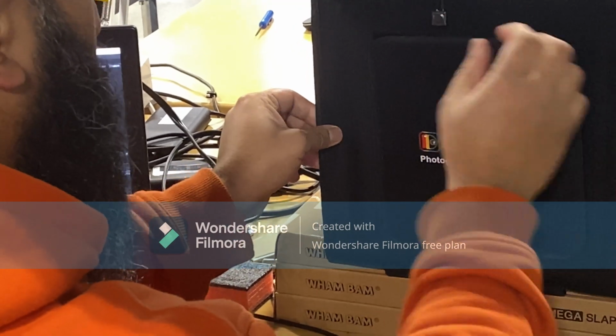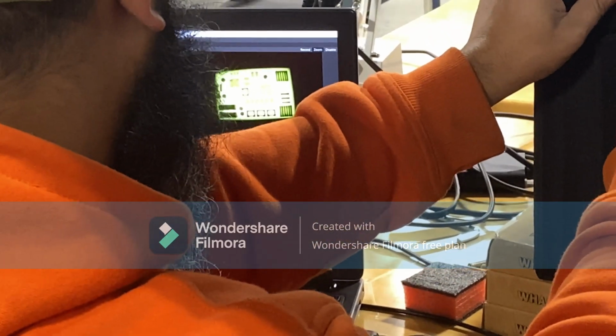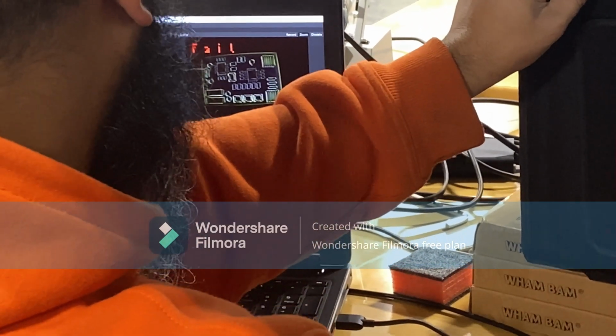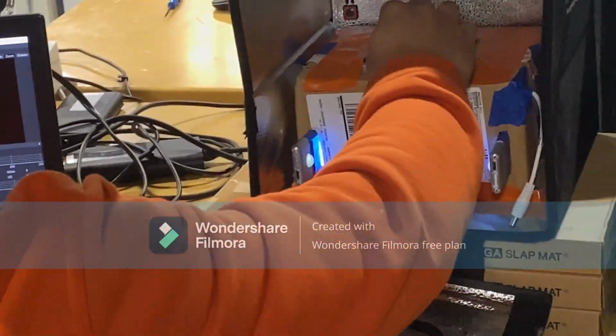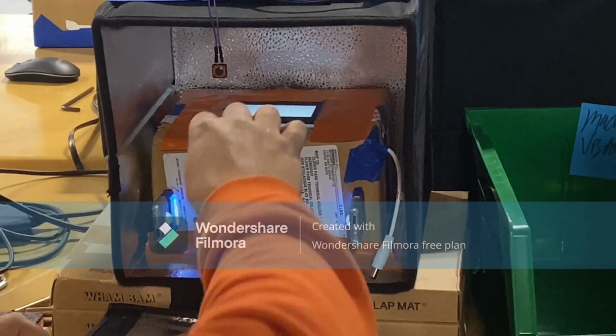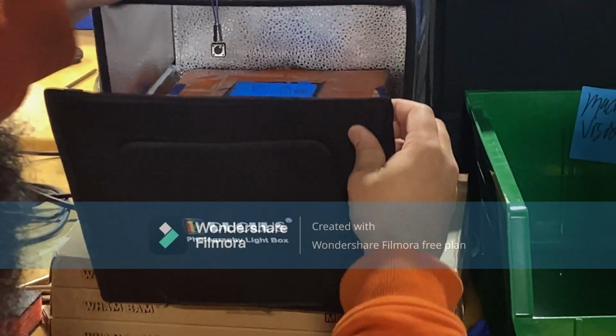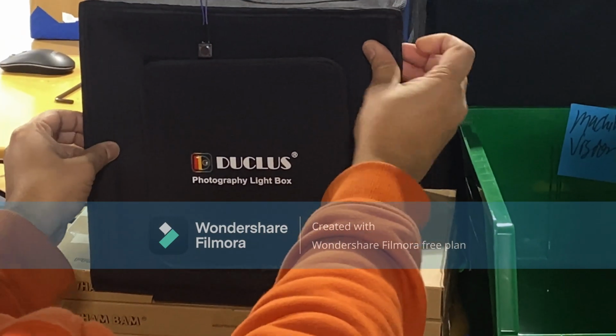The requirement for the light box was due to the vision system's sensitivity to ambient light and the way it recognizes objects. The light box isolates the environment and allows the image produced by the camera to become more stable. The light box also serves as the housing of the camera and allows the camera's stabilization fixture to be mounted.